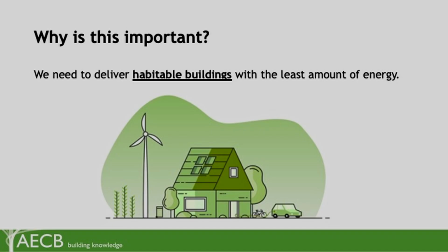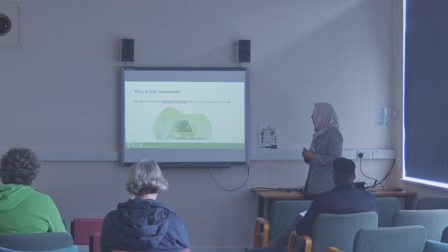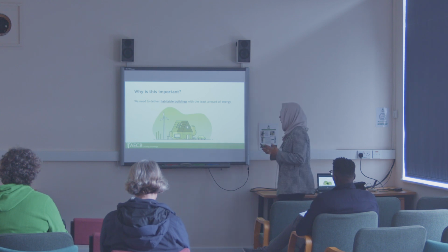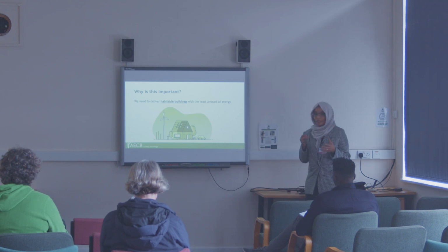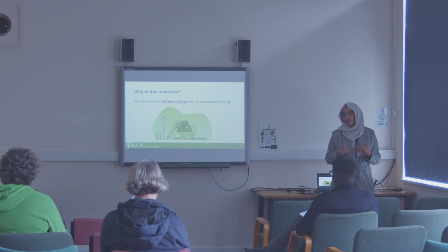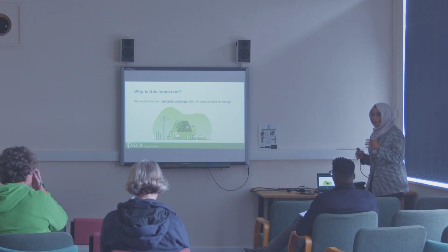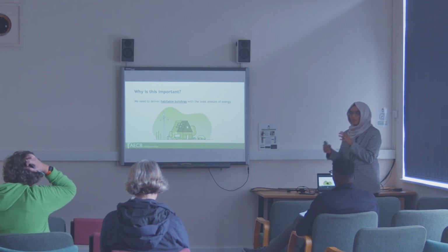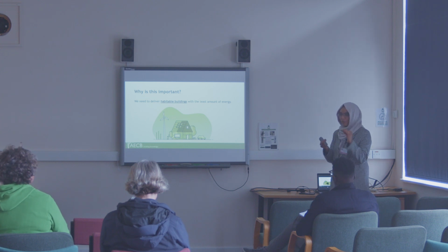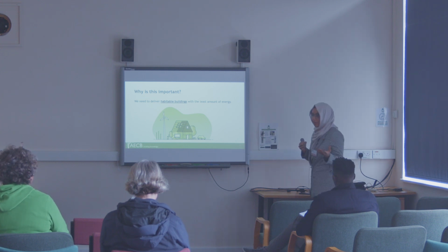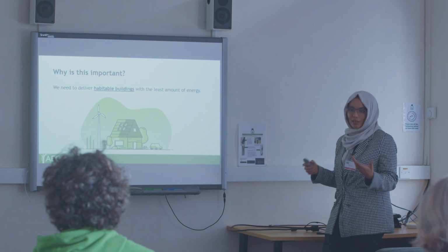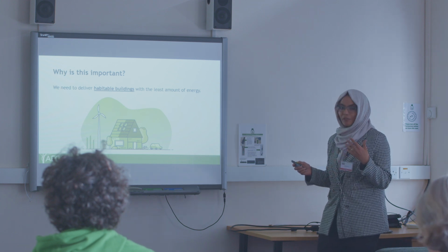So why is this important, and why is it relevant to sustainable buildings? Because you need to build habitable buildings. You can't, for example, put no heating in a building and say, oh, well, it's saving energy because there's no heating. So you have to make them habitable. And that definition is a key part of it, and it has a huge impact. There was a recent study about something called dynamic set points, where instead of having the same set point the entire year, you change it based on what temperature it is outside, and it has done massive savings in building energy. So it's a huge part of energy savings.